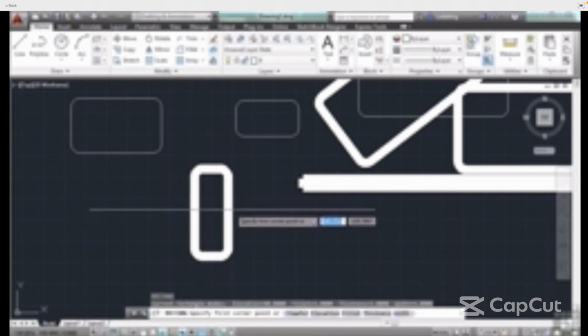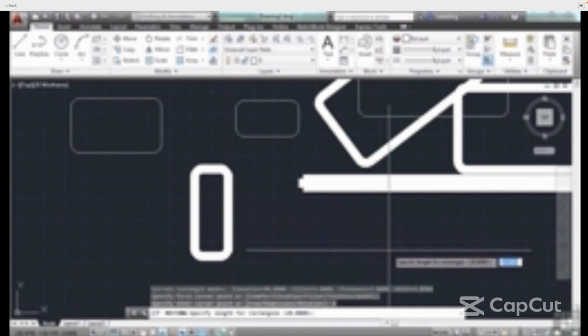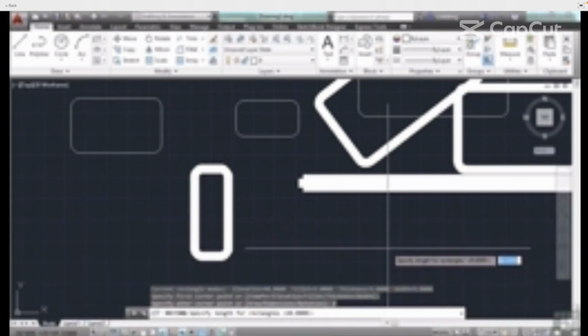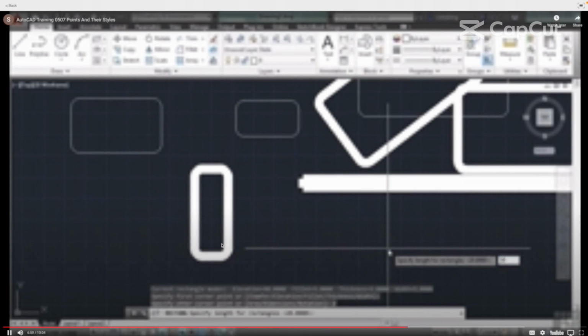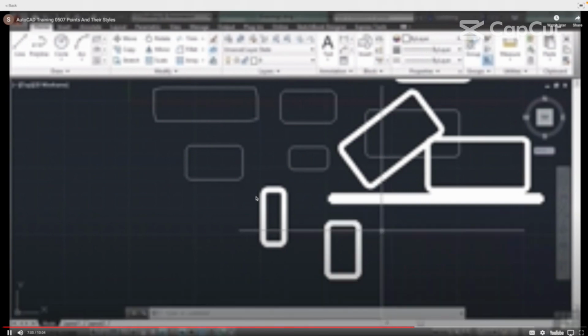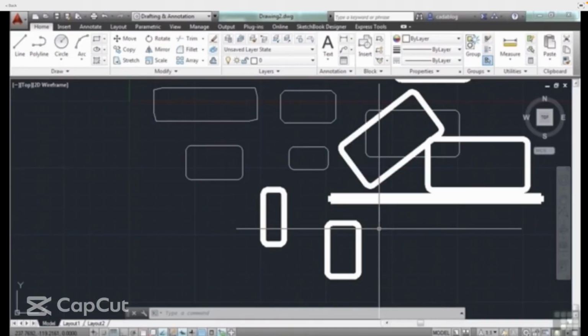And then the last option that we'll show here is the dimensions. The dimension option is very similar to when you entered in the lengths and sides earlier. So you'll just be able to type in the lengths that you want, say 30 and then 50, and it locks it in for you. Option is a leftover from before AutoCAD had the dynamic input, where it was very easy to type in your length and width. So you probably won't ever use that, but I wanted to show it to you in case you were wondering what it was.